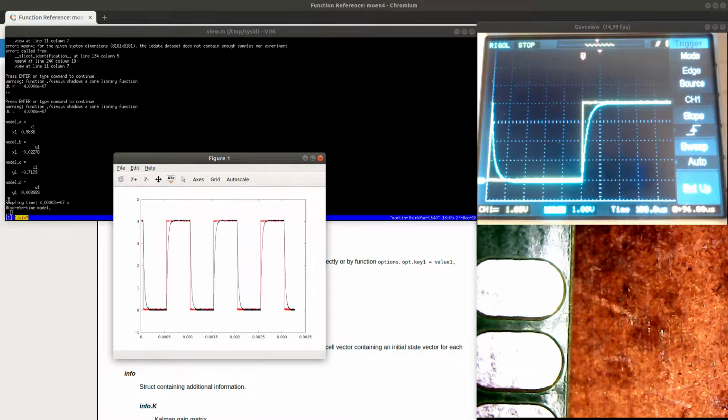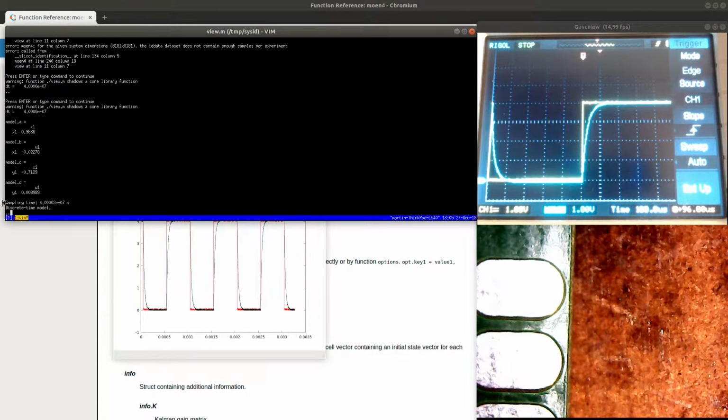It's very important to see that this is a discrete time system, because this is a state space model, and if you try to call state space to transfer function on the discrete time model, you're going to get values for the discrete model. You cannot use those values as the coefficients in a continuous transfer function, because it's going to be completely messed up.